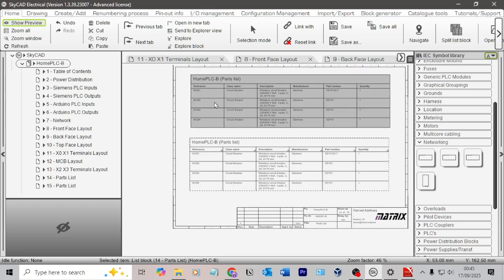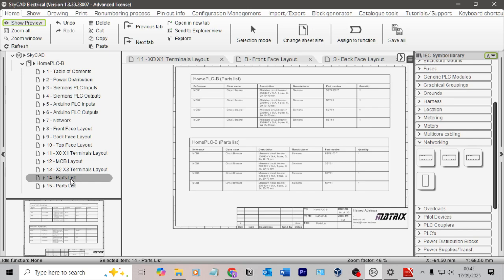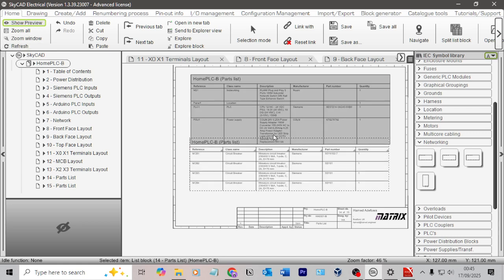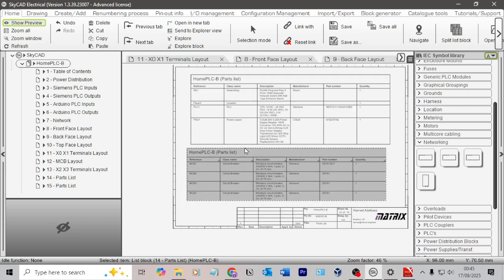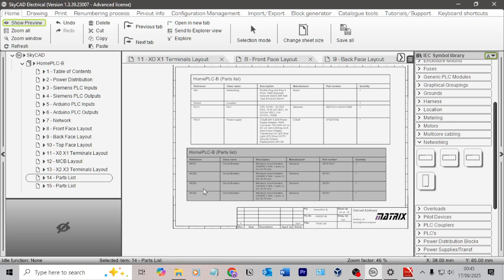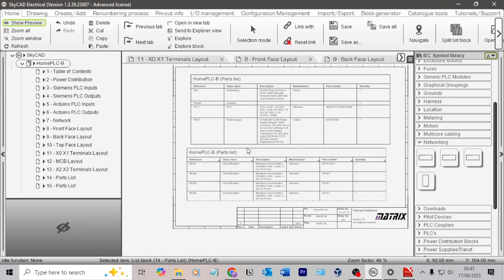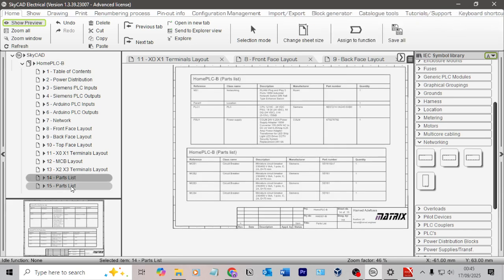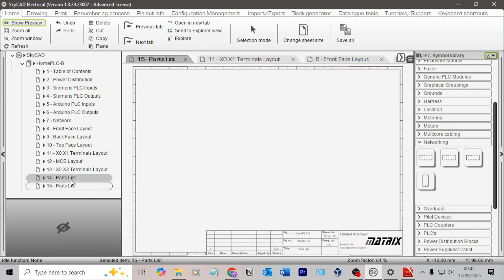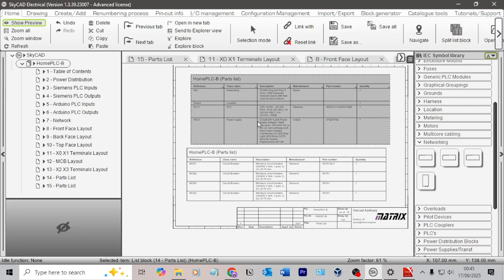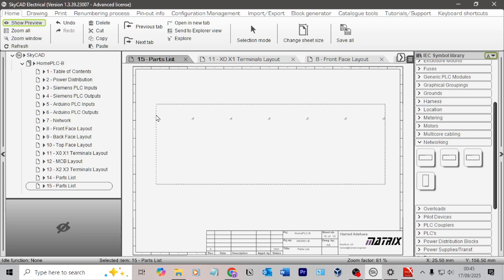So you can see there, why is it split? Interesting. Something's gone wrong there. Okay, there, cool. So you've got MCB1 and then NS1. We want this one on sheet 1. All right. So sheet 2, delete this, take this, copy that on there.